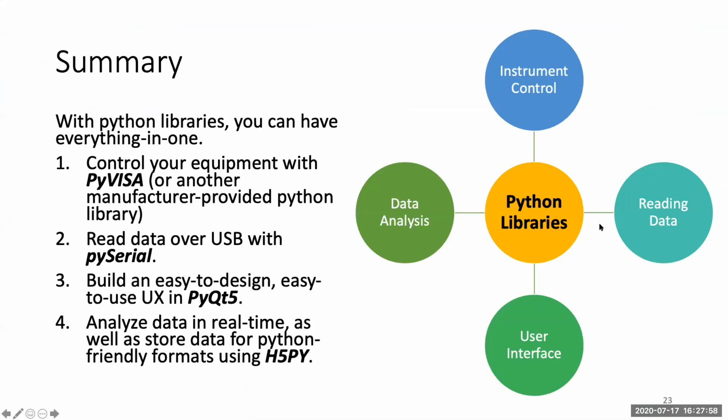Okay. So in conclusion, with Python, you can really have everything you need in one program. PyVisa and custom manufacturer-built Python packages allow you to control your test bench. You can communicate with your test board using PySerial. You can build a user interface with PyQt, and you can analyze your data in real time with packages like SciPy, Matplotlib, and store it for later using H5Py.